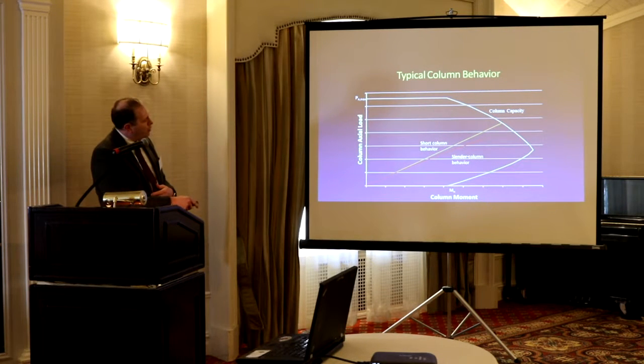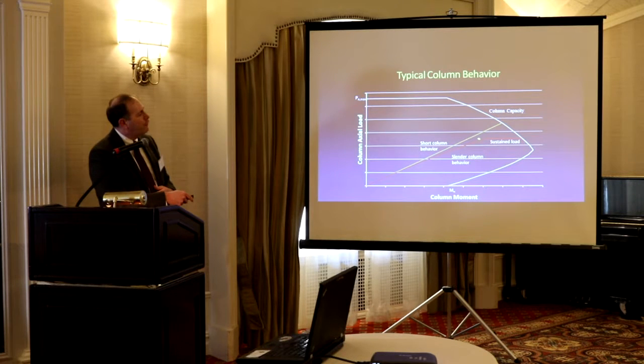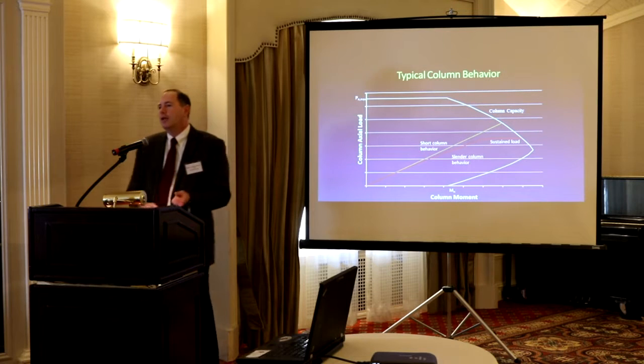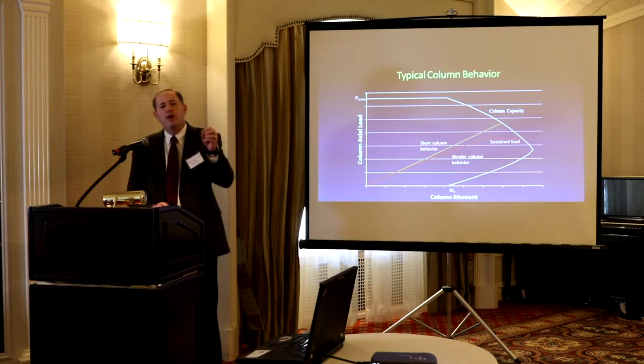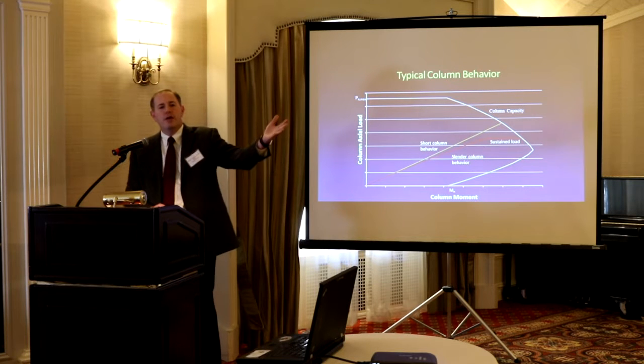So one other problem though is, that would be great if I'm just loading up, but we often bring loads up to a certain value and sustain them for many years. And so that's the sustained load effect. If it came over here and sustained and hit the curve, that's often known as creep buckling. We don't want that in our buildings, where I'm at a load and all of a sudden, over time it continues to deflect and then it fails.